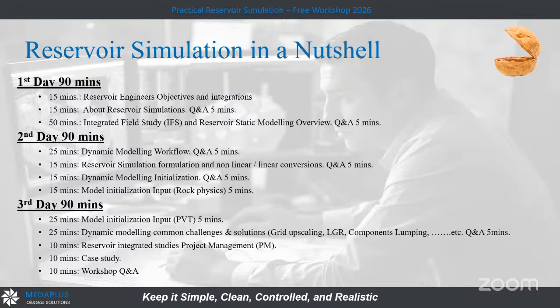And finally, we discussed the interfacial tension and how it affects the wettability and the capillarity in the model. We have homework to do, where we have the capillary pressure curves and convert them, and we discussed the Leverett J function to have capillarity in each rock type or each cell that has different permeability and porosity.